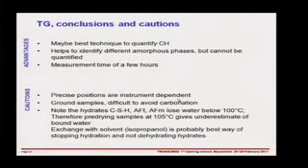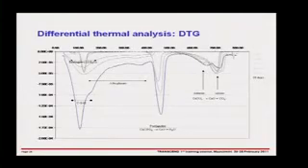The disadvantages, and this is particularly a disadvantage here, are that every single instrument, every kind of setup changes slightly the positions of the peak. So if you go to a textbook and you say, oh, okay, I expect to see this peak here and this peak here, you can't guarantee that that's going to be the positions you're going to see in your material. And they can vary by a lot, by sort of 50 degrees or so. It's not too much of a problem, because if you're just dealing with cements, everything tends to look more or less the same, and therefore you can work out what things are. But don't slavishly follow temperatures or positions that you read in the textbook.